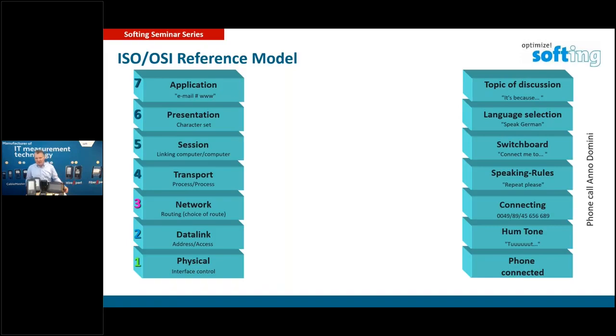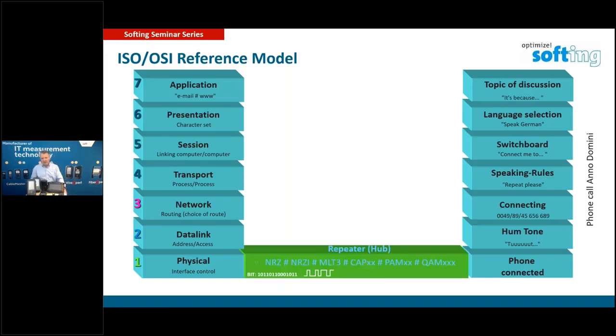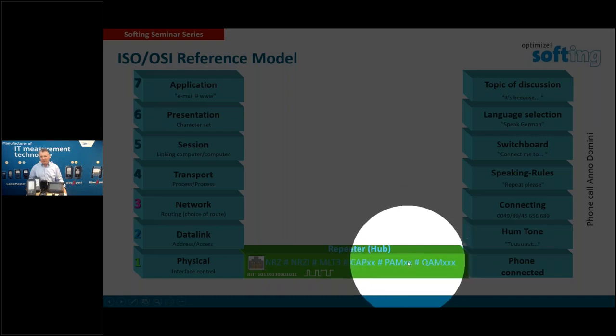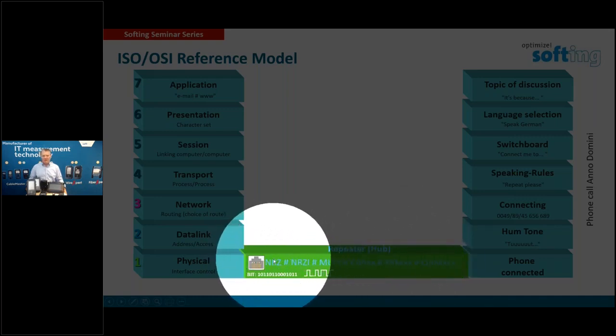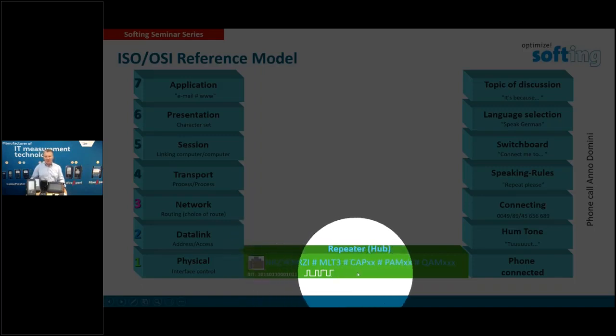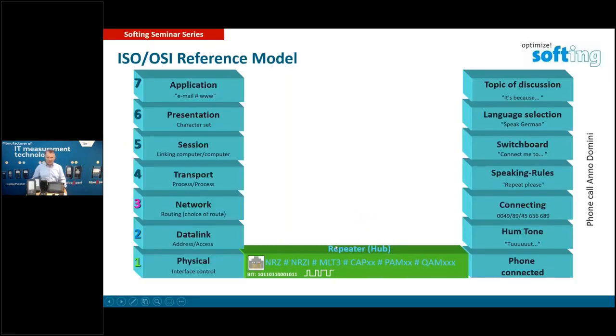And you have this physical layer, and if you want to see what happens on the physical layer, here we have the data modulation. Because if you transfer 1 gigabit, you will not need a 1000 megahertz bandwidth, because we're using modulation like phase amplitude modulation, or a simple one like NRZ or NRZI modulation, or MLT3, which becomes important for 100 megabit transfer.